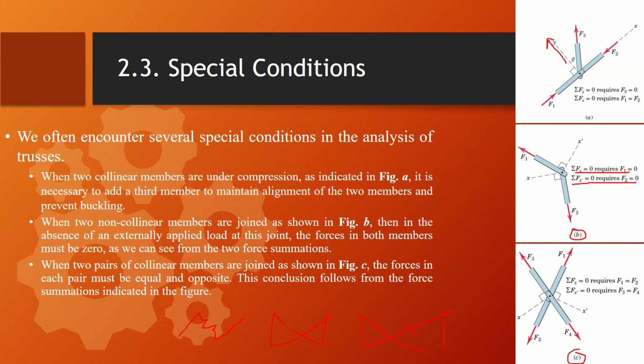When this choice cannot be made by inspection, we may arbitrarily select the member to be retained. Now, if the assumed tension turns out to be positive upon calculation, then the choice was correct. If the assumed tension turns out to be negative, then the opposite member must be retained and calculations are to be redone.